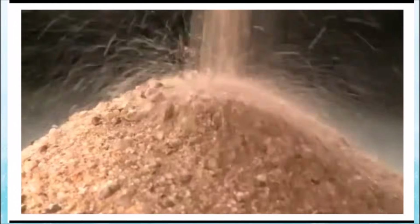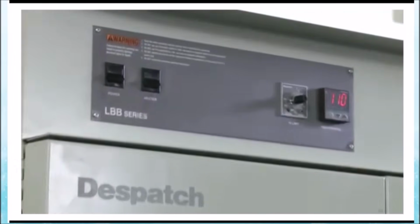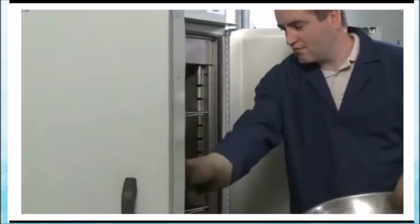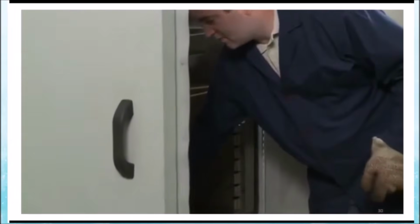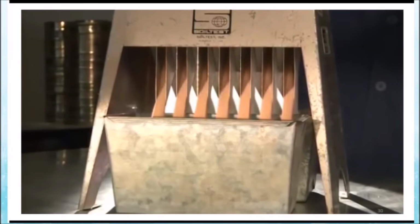If you desire to use method A, you must first dry wet samples to the SSD condition or drier. But when doing so, be sure that your temperatures do not exceed those specified in the test you will perform on the sample. Method A employs the use of a mechanical splitter having an even number of chutes, not less than 12, which discharge alternately to each side of the splitter.